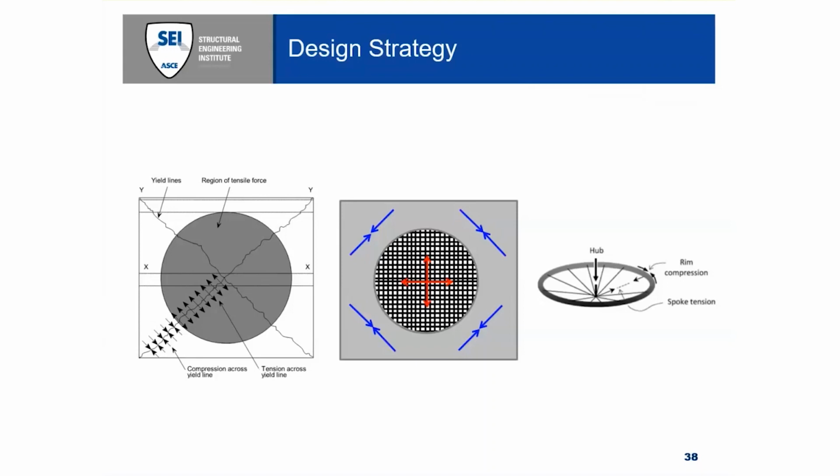And also, we don't want the slab undergoing a crack geometry that would become unstable. So we need to control the deflection of those periphery members. But we can allow for some deflection. It just is engineered, as I'll get into.